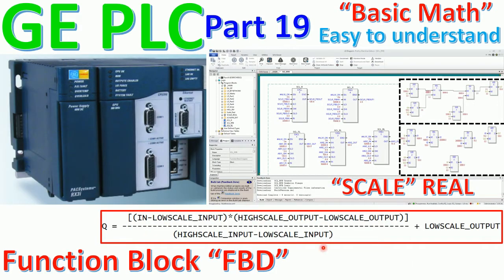So for today we will learn about the basic function block, where we will create one block for the scale real. And this is the formula, the same as the previous video, but this is a function block. So let's go to our software to create the sample function block for the scaling.